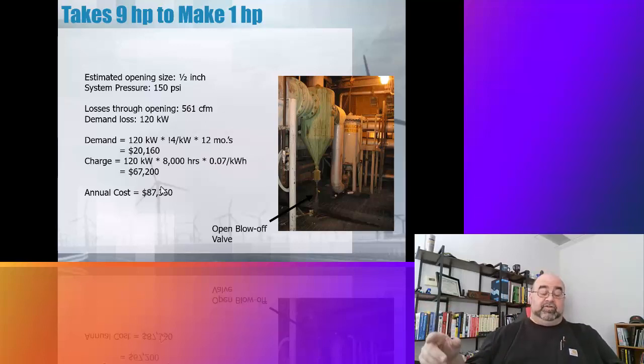The compressors do not have an opportunity to unload. Basically, the compressors were always on and overloaded. That was one of the things. It went right into the motor side, was the number of times they had to replace motors, repair the compressor, repair lines. Compressed air is also used for bag houses, and they had a big need for a compressed air strategy. And that's one of the things that the software and the manuals provide that again, are free to put that together. There were 250 horsepower electric motors running on 2 Sullair compressors. During the course of the study, they were found to be overloaded.